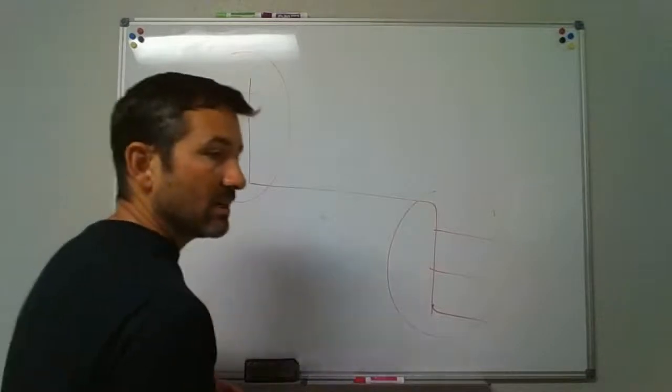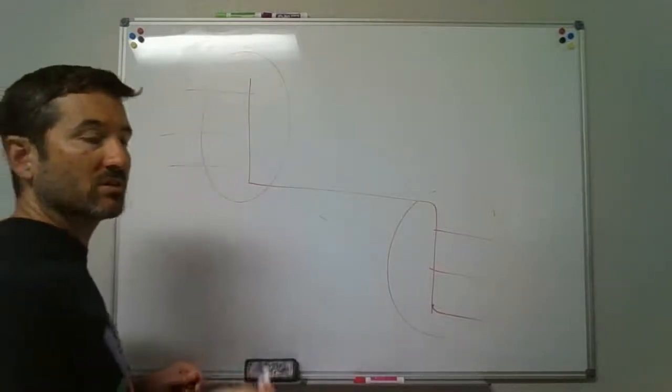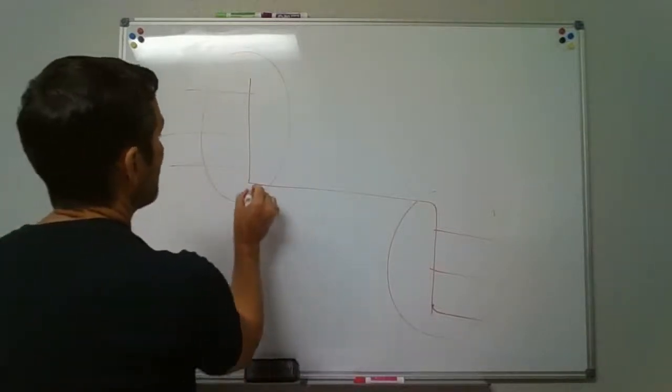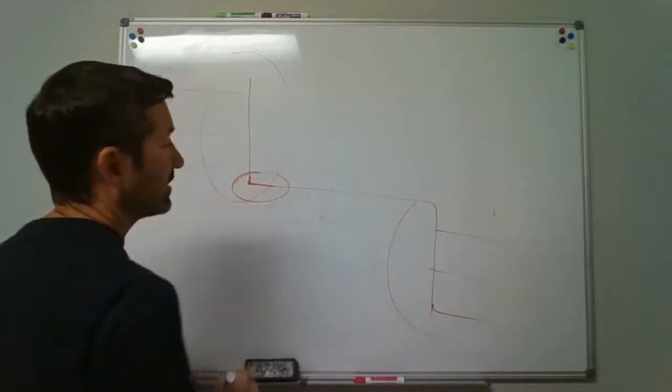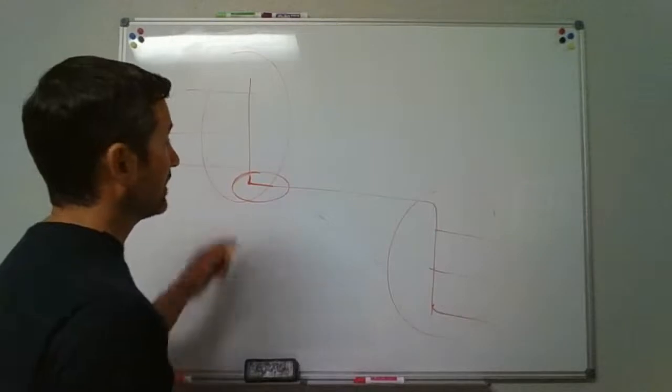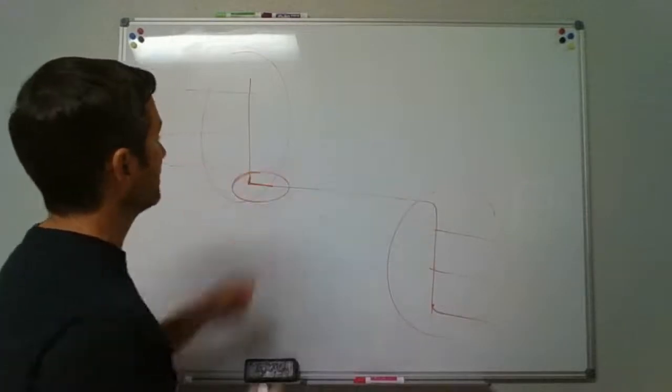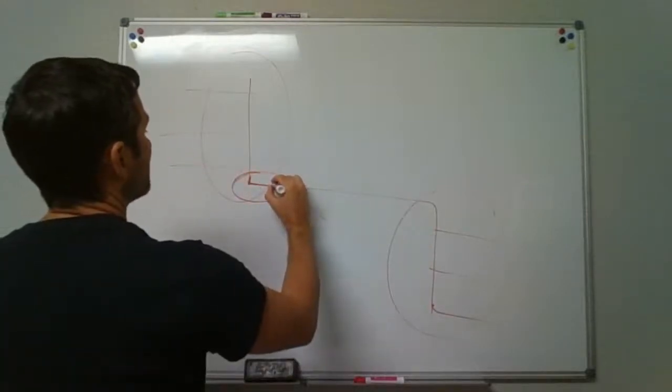You're going to do your vent stack just like we've already talked about and make the connection. They're going to say you're going to call this the base of the stack. Okay, the offset portion is going to be considered the base of the stack.